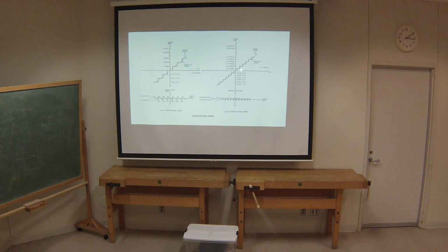And now we've halved the maximum distortion. Now, instead of having half a volt of distortion, we have a quarter of a volt. And if we keep on adding bits, that error or distortion is reduced. Now for audio, we assign almost always 16 bits, which translates out to 65,536 little steps.